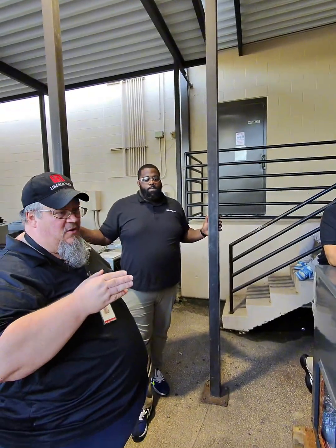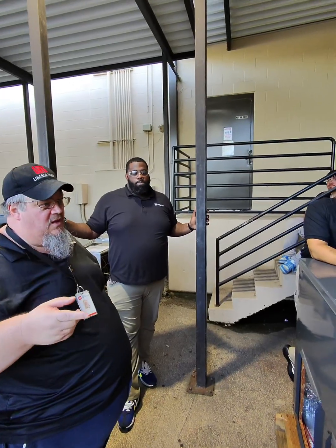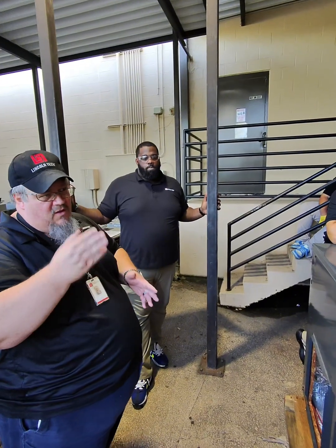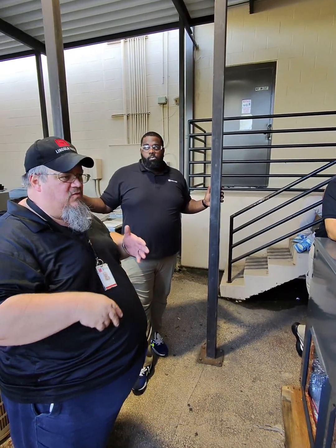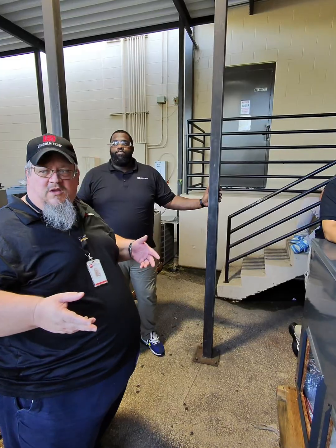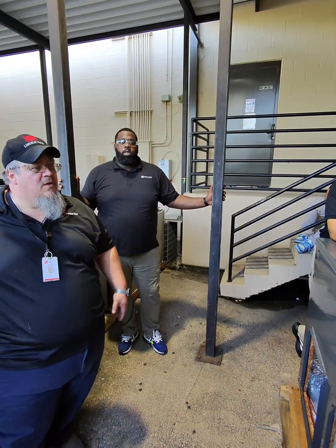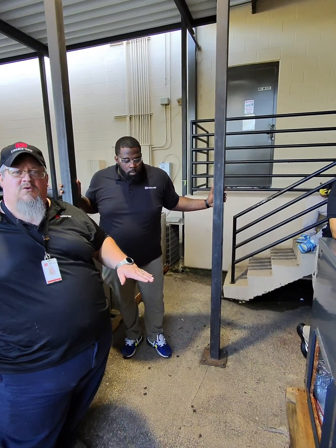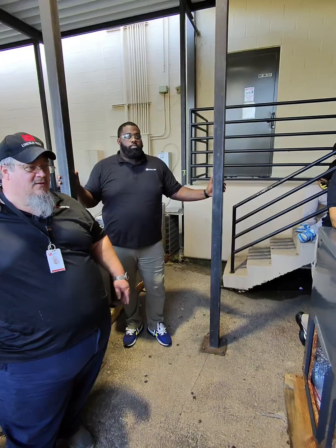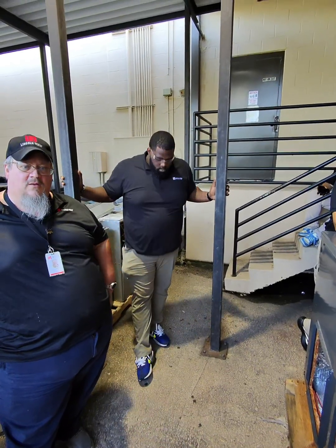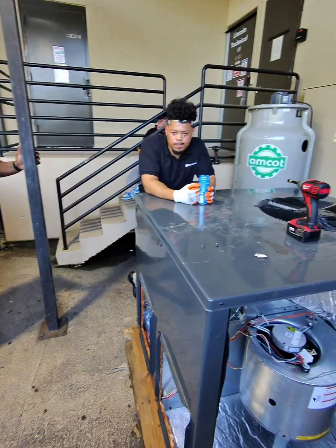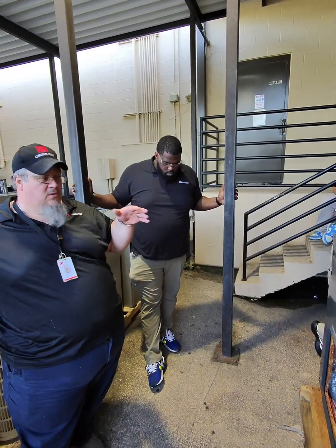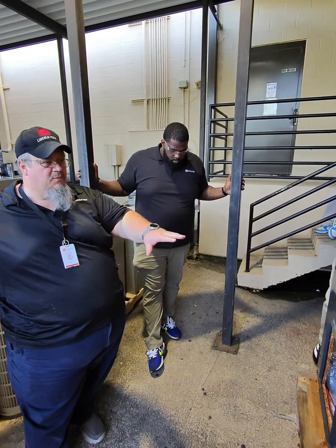And just about all manufacturers have the same sequence of operation. You may have low fire, high fire, you know, your W1, W2. It's going to work the same way. It's going to call for W1, W2, some's time delayed. So different manufacturers are going to control it in different ways, but you have the basics. You know basically what's supposed to happen, the fundamentals. You know what the safeties look like. You know where they're located, right? Yes, sir. So whenever you see a new setup, don't freak out. You just take what you already know and apply it to what you're working on.